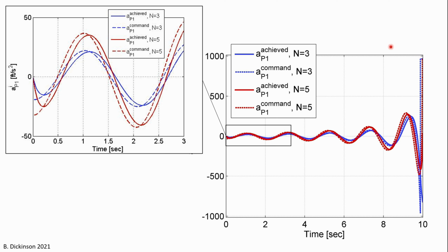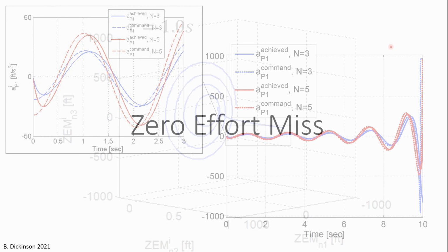And while it's not as apparent here for this 3-dimensional example, comparing this case to the 2D accelerating target case we've previously looked at, the same trend is holding. The larger the navigation gain, the larger upfront acceleration that's required, but it pays dividends later on where a collision triangle is better established, and so less acceleration is required in the final moments of the engagement.